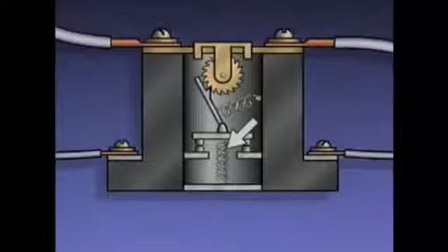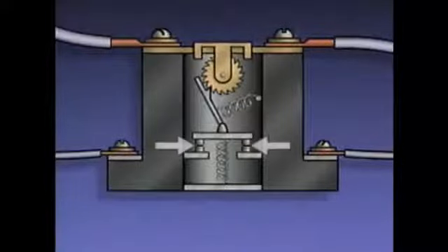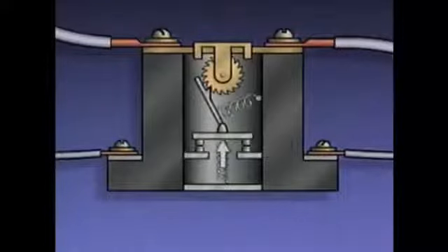While the solder is solid, it prevents the ratchet wheel and the rod from turning. As long as the ratchet wheel and the rod do not turn, the contacts remain closed, and a complete circuit to the motor controller's main contactor, or M coil, is maintained. The contact spring is positioned so that its force works on the mechanical linkage to attempt to turn the ratchet wheel.